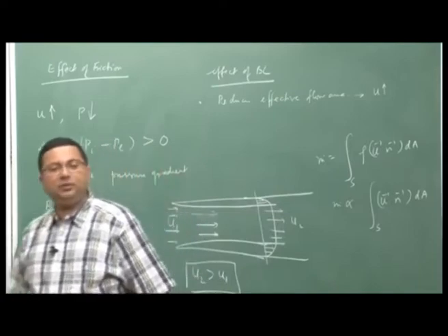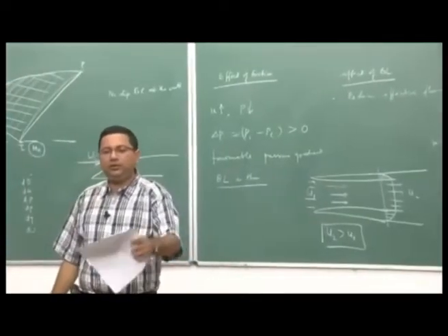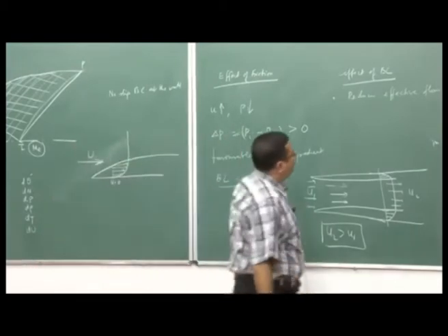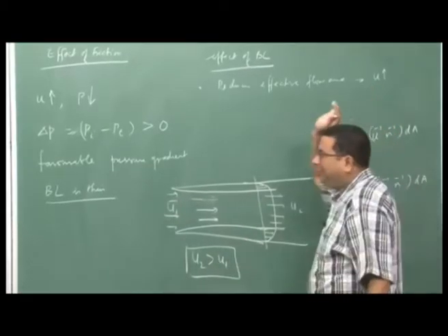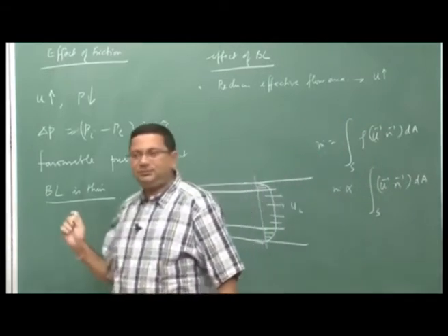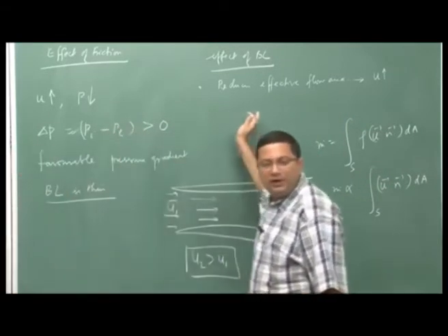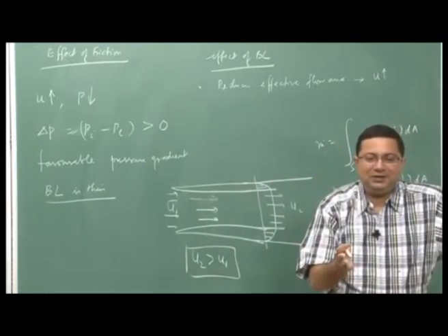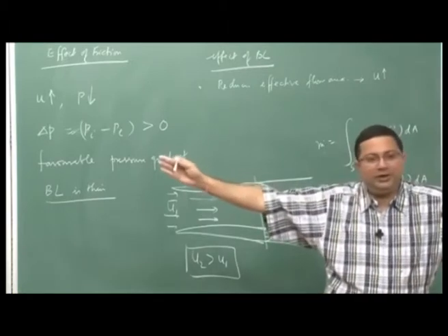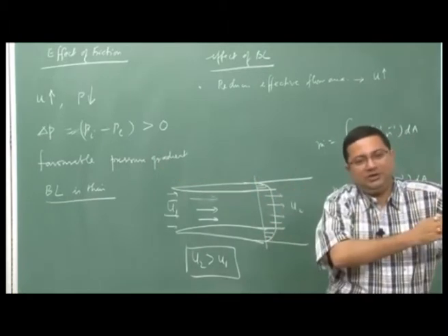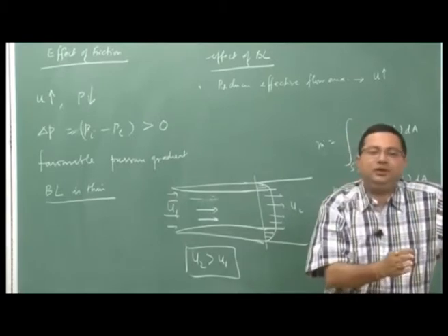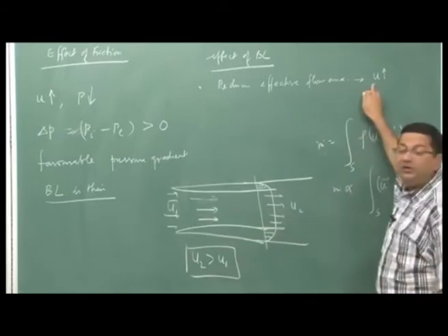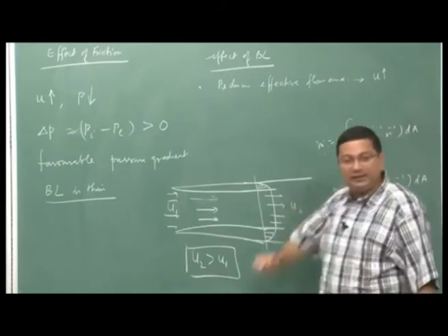Either we increase the velocity or mass flow rate, but mass flow rate is coming from some source which will not be affected. Okay. So, therefore, velocity is going to increase, because the mass flow rate is essentially dictated by your throat condition, right. So, we have the throat before it, the throat condition and the combustion chamber conditions completely fixes the mass flow rate, that will not change. So, if the mass flow rate is not changed, the only thing is that your velocity is going to change, velocity is going to increase.